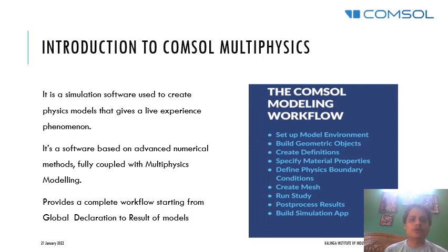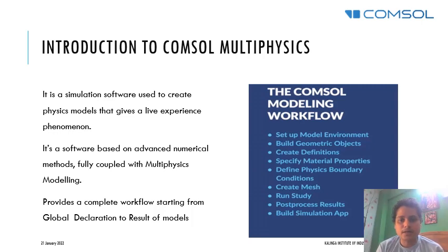First, you have to open COMSOL Multiphysics. Once you open it, you have to take the 2D geometry. Once you take the two-dimensional geometry, you have to go for the study. What kind of study do you need to do? You have to study the electromagnetic waves. Once that is done, press the done button, and finally the COMSOL application will open, and the interface will open, where you will see a number of boxes.